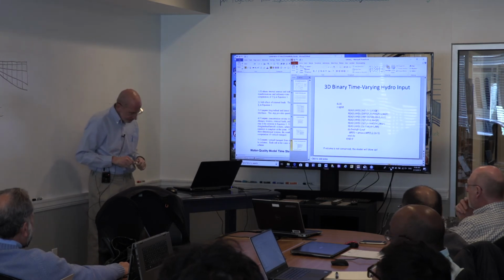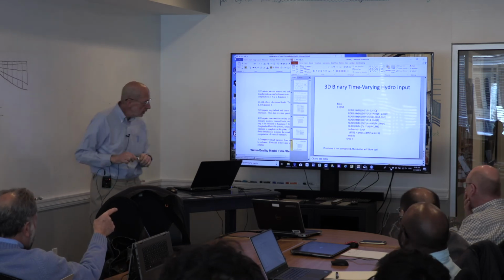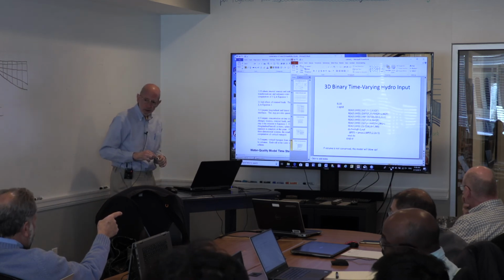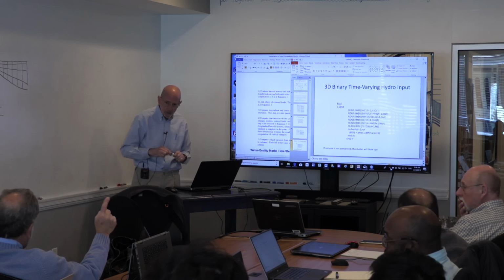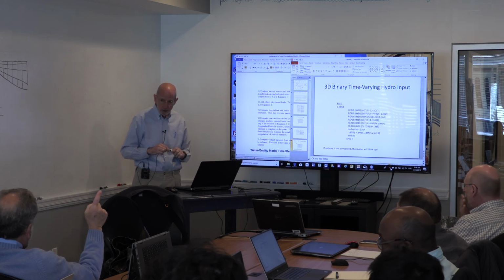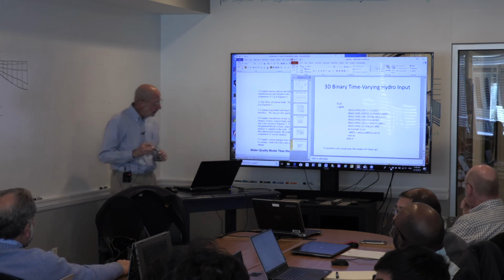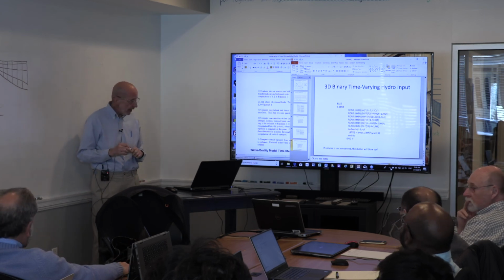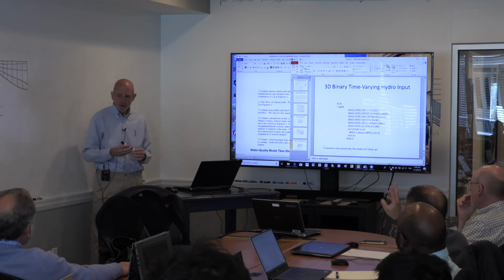Let's look at that. Sorry, just reading the literal flows. Which line is that? QLIT. You can only read literal flows from 1 to NB, which I presume is the number of boundary. NB is number of boxes. Oh, so it's for all of the boxes. So you could read a literal flow for any box. Actually, you're compelled to specify them for all boxes, but if they're zero, they would be zero.